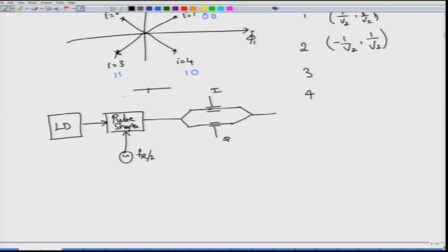All you have to do is, whatever the symbol sequence or the bit sequence that you are getting, you essentially put a demultiplexer after the symbol or the bit source, and then extract the I bits and the Q bits. I am writing it in such a way that I am connecting this I and Q. So, I have the I bit here and the Q bit connected. Please note that this is actually a jump connection here, it is not a straight connection.